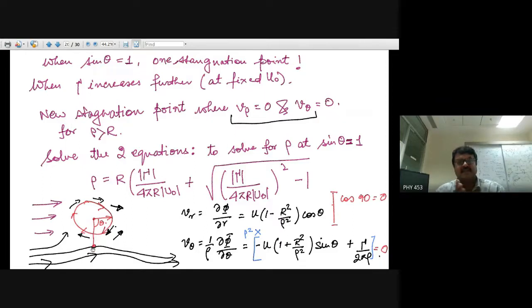Here you are doing ideal Euler flow, where you are neglecting viscous terms, or even if there were viscosity, you assume a very small boundary layer, and outside that Euler flow is valid. So very close to the surface, you will have a finite velocity of the fluid. If you have perfect Euler flow, there's no friction, there is no viscosity.